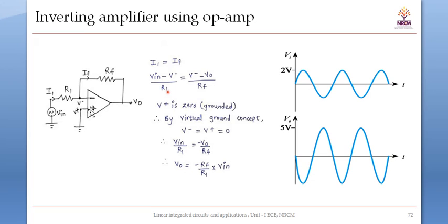If the non-inverting input terminal is at 1 volt, then the feedback is provided such that the potential here will be 1 volt. The output is going to provide the negative feedback such that VID is equal to 0.